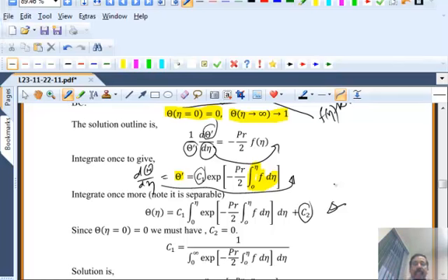And we need to now evaluate the two constants, C1 and C2, from the boundary conditions. Obviously, at the plate, when eta is equal to 0, what is the integral? Integral from 0 to 0 would be what? 0, because it's area under the curve, but there is no limit. So it's the same point. Okay, so that means 0 is equal to C2, because the integral itself will be 0. So that tells you that C2 is equal to 0 from one of the boundary conditions.